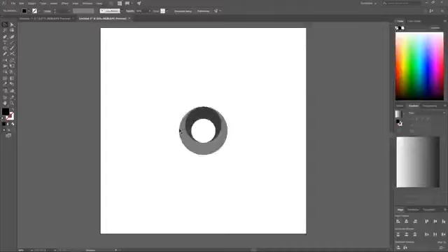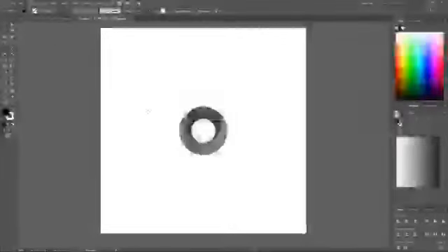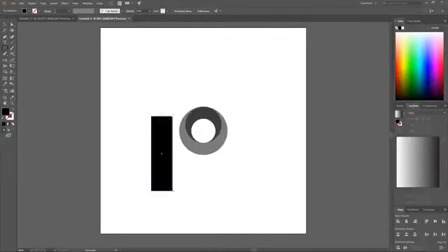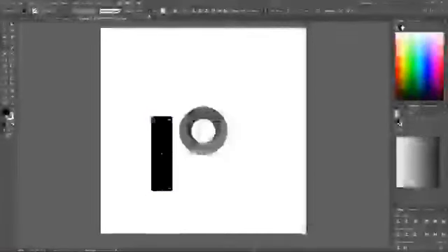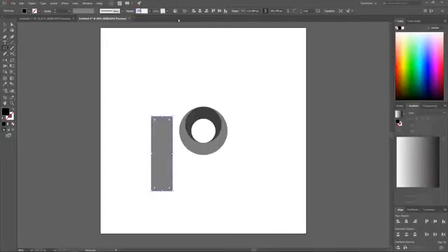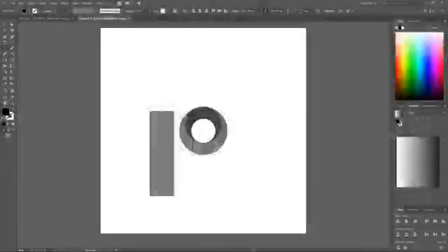What I'm going to do now is create the tail end over here. I'm going to click and hold on the ellipse tool until we get the flyout menu, and then we can choose the rectangle tool. I'm going to click and drag to create a rectangle like that. I'm going to bring the opacity of that down in half, and make the width of this 150. Over here on the inside of this rectangle, you'll see these little round anchor points. I'm just going to click and drag that in until those edges turn red like that, and then it's going to become rounded.